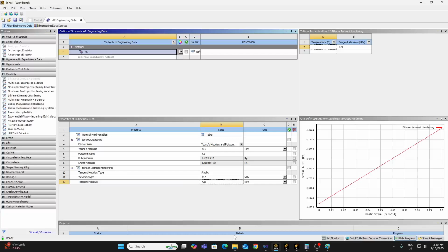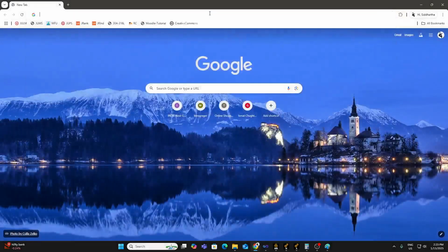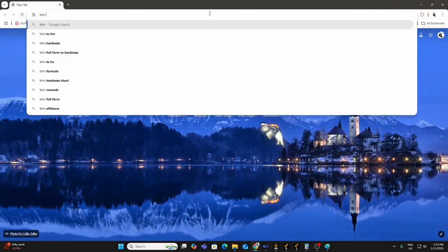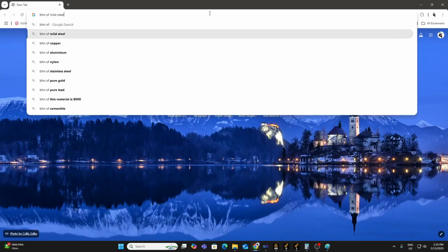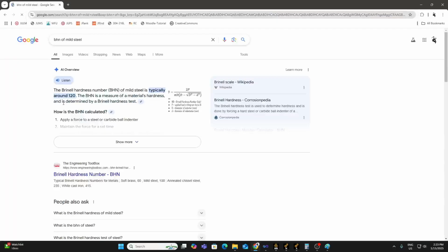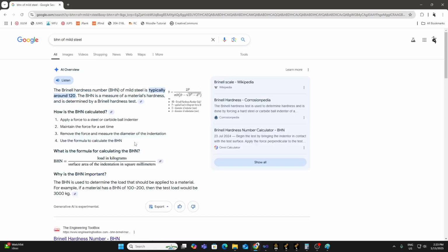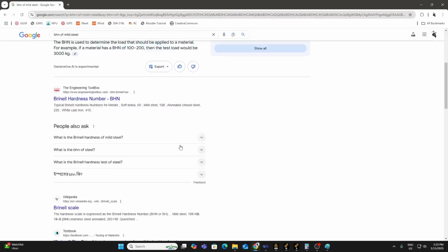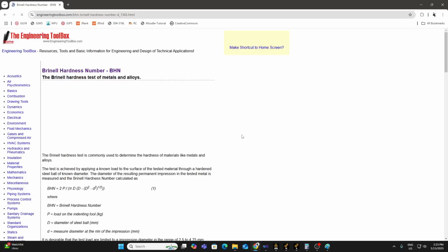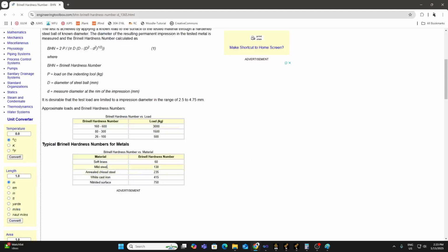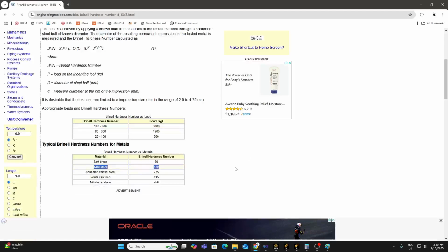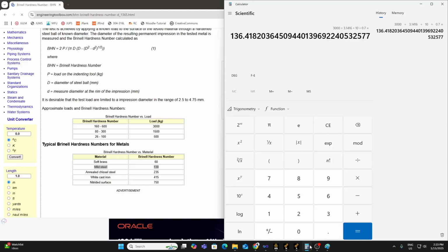Okay, so if I go to internet and search for BHN, Brinell hardness number of mild steel. Okay, and this is the answer that I get. It is typically of the order of 120. Okay, so I can say we are very close. Okay, so we are not getting an absurd number. Somewhere I observed that that value typically lies between 120 and 130. For example, if I click this particular link, that tells me mild steel has a Brinell hardness number of 130, and considering the value that we are getting is 136, I should say that we are very close.